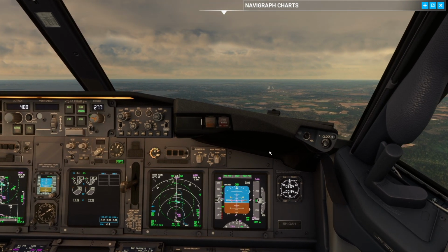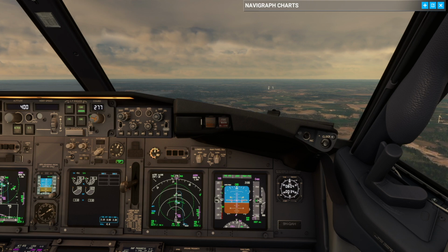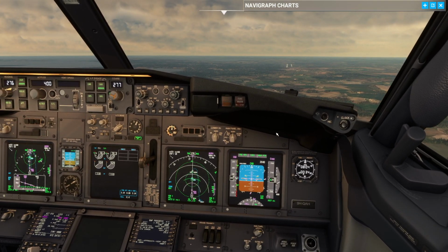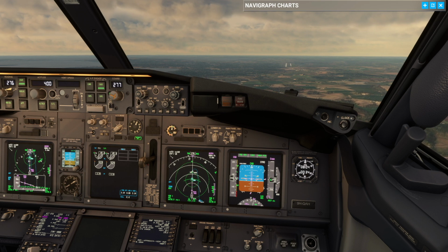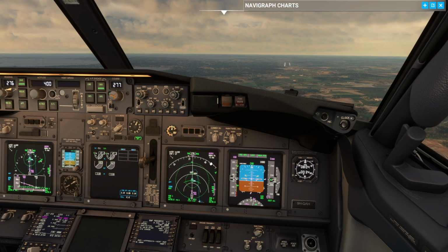Good. So now the next job is for the pilot flying to do his checks above the final approach fix. Cabin crew, seats for landing. Notice how we didn't use the approach mode, guys, on the standby altimeter. That's because it has only reference to the localizer and glide slope. We don't have any of that.